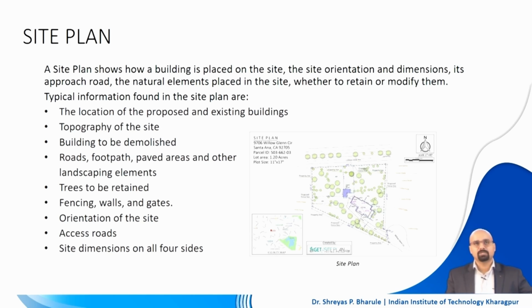Next is your access roads. Your access road which is outside the site is to be mentioned. On one side of the site, in most cases, you will get an approach road, or an access road, through which you create a site entrance, right. So, that is to be represented at complete scale, and it may be truncated on the two ends to the extents of your site, like done in this fashion, where the road ends here. So, you might introduce break lines like this on the two ends and you represent the complete access road.